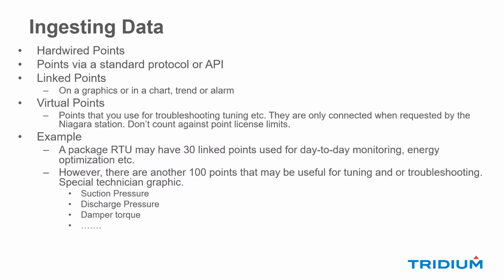When we ingest data, a lot of it is now hardware points, and that's the way it used to be. Everything went in through an IO module and it was a hardware point. But today we have points that are software, whether they're coming in via BACnet or Modbus or some other protocol. You know, a VAV box, we might normally deal with 10 or 20 points, but there's 150 set up and different types of points that's available even in a VAV controller. So think about a plant controller or a chiller controller that could have hundreds of points that we may not need in day-to-day operation, but when there's an emergency, we may need to know what's going on deep within that